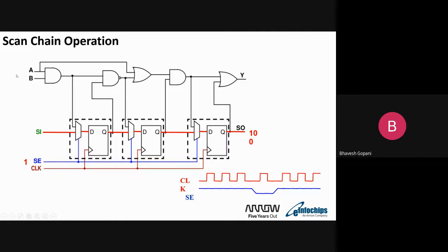So what I need to do is another fault test, that is the transition fault. Why do I need to do the transition fault? First let me tell you what a transition is, then I can tell you why. In the transition fault there are two possibilities. As the name indicates, the data at the input transitions from 0 to 1 or from 1 to 0.